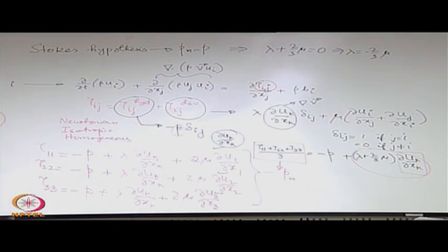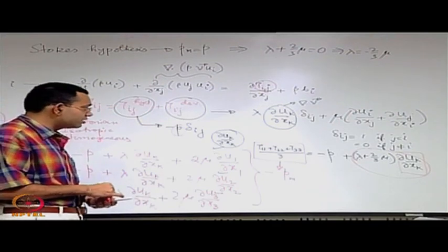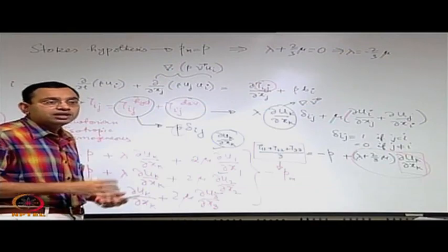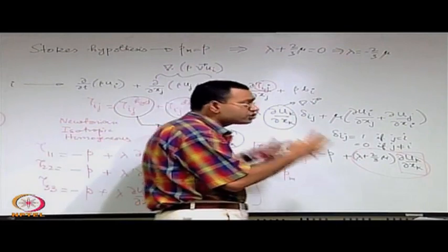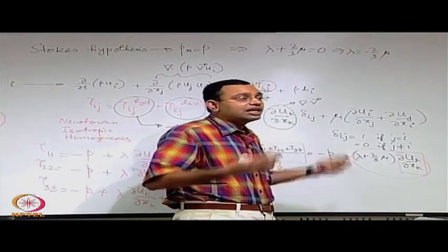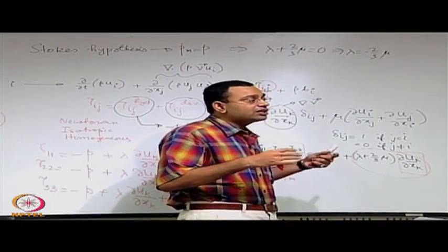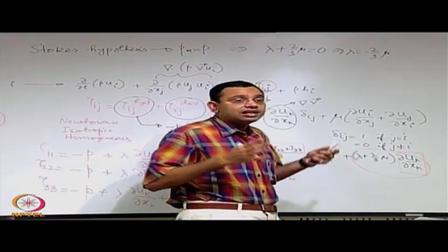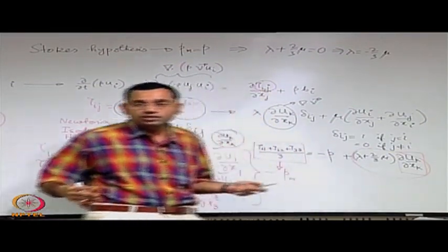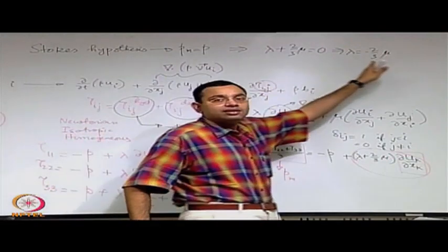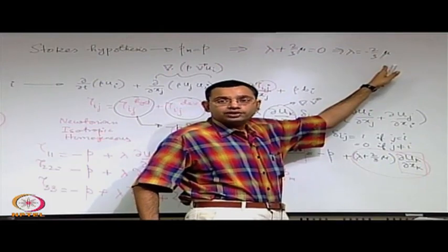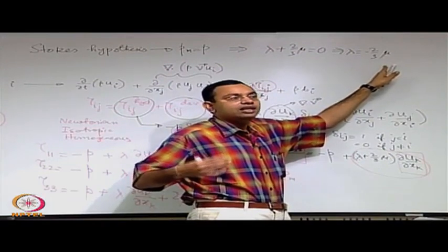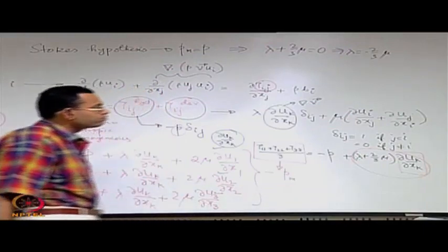There are certain fluids for which we do not care whether this is obeyed or not. What are those special fluids? One we discussed is monoatomic gas. If you have a monoatomic gas, it has to be obeyed, so it is not a hypothesis anymore, it is an exact reality. So for a monoatomic gas this will be exactly valid, and therefore no question of approximating mechanical pressure with thermodynamic pressure, they are exactly equal for a dilute monoatomic gas.